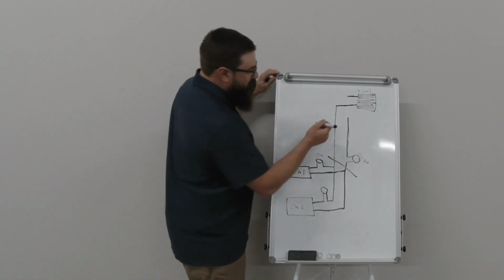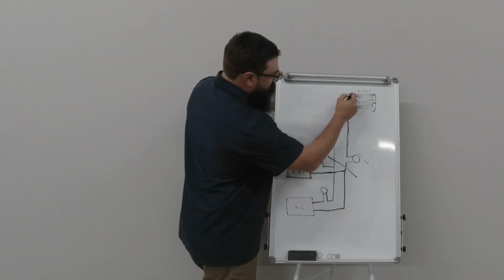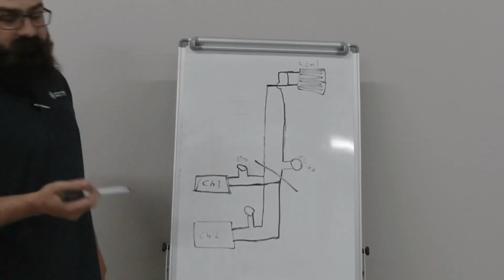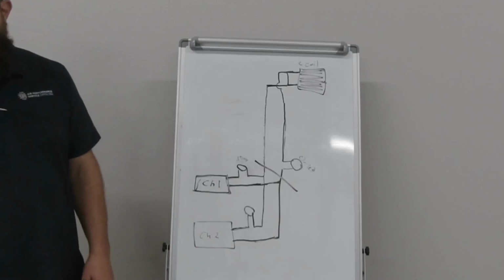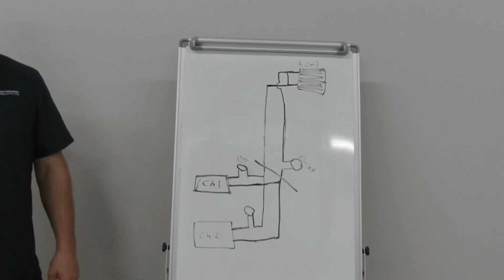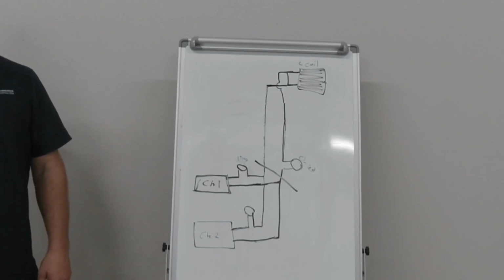So what happens is we end up with a return side of your coil, which is typically where your valve is, because you always want your supply coming into the bottom of the coil, and then you want your return at the top. That way your coil is always full of water, right?